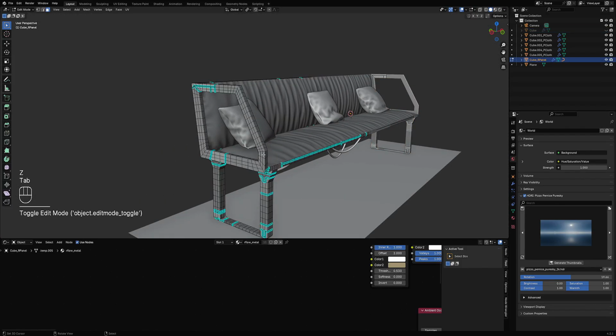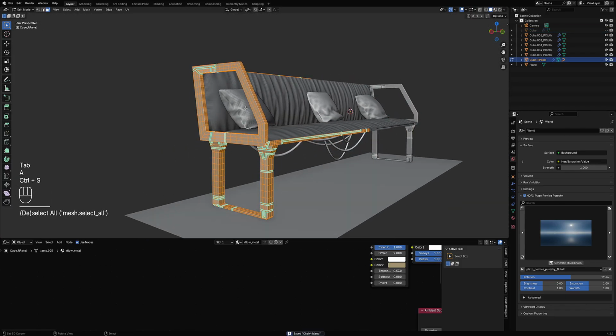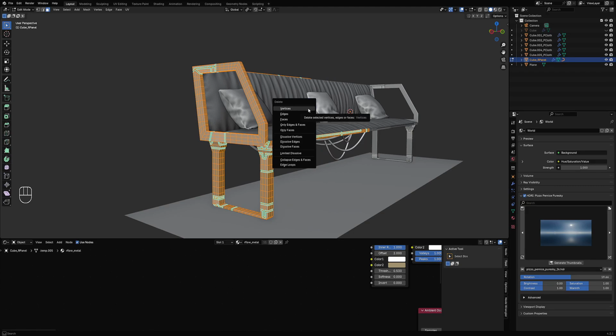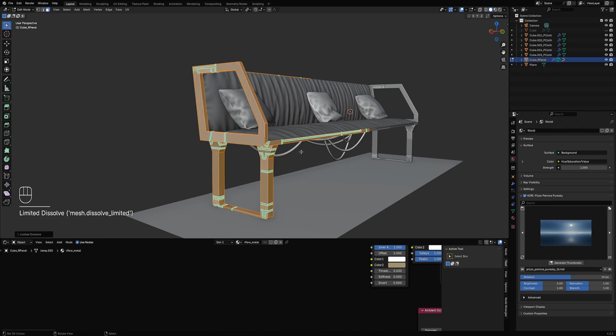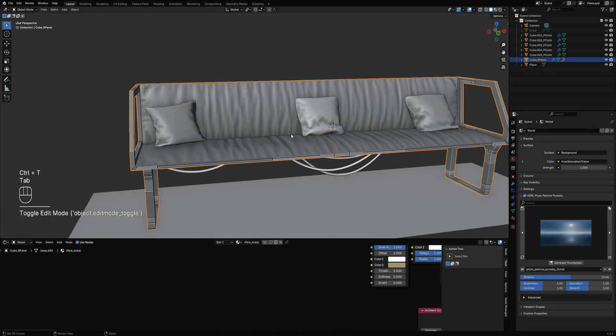You can, of course, make this lighter since this is angular hard surface. You don't need to animate it. It doesn't need to jump, smile, frown or bend. So limit dissolve, Control, you can leave the n-gons as they are, or Control T to make it lighter for the asset browser.